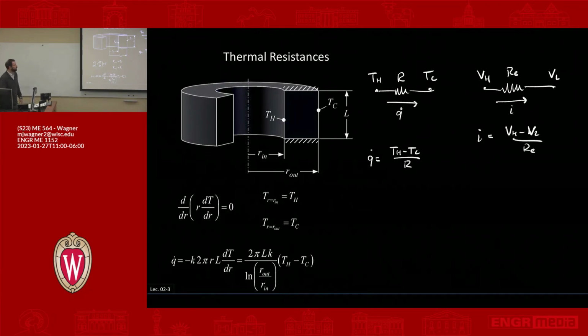All right, so the idea of the thermal resistance comes into play in that if you can find an equation that looks like this, a difference of a potential of temperatures and then some constants multiplying it, it doesn't matter if they're numerator or denominator, we can call that 1 over R. And that becomes our thermal resistance.